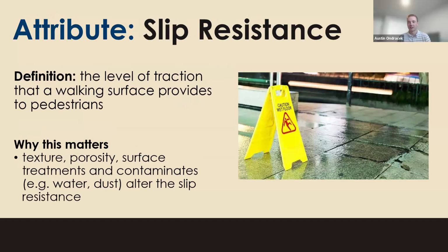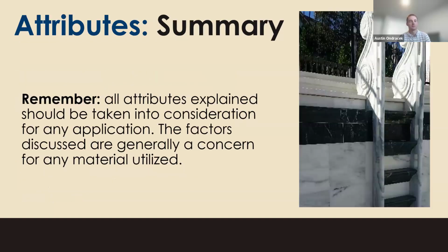Slip resistance is another thing. Natural stone, the texture of it, unless you surface it differently, is really inherently built into it and doesn't have any slip in it, which is a huge plus. That's why you'll see a lot of paving applications of natural stone in malls and walkways, to really reduce any issues. Even if there is water on it, it will still stay textured, with no issues of liability coming your way, which is something none of us want. So that's a huge plus about natural stone, it's naturally slip resistant.